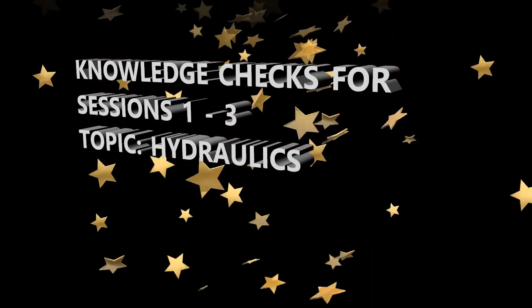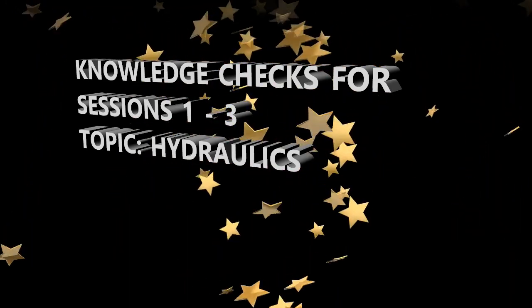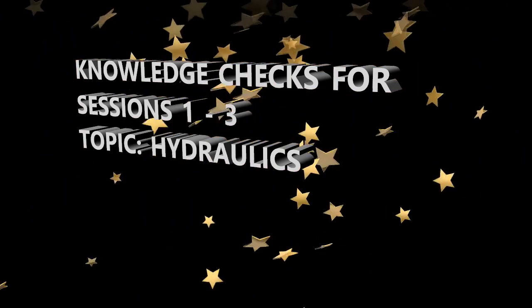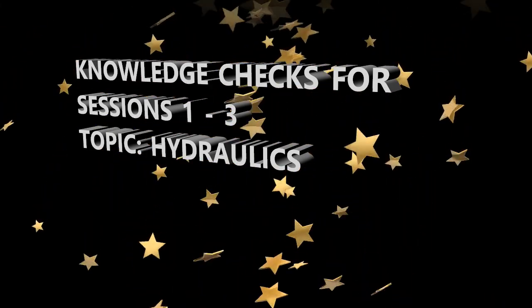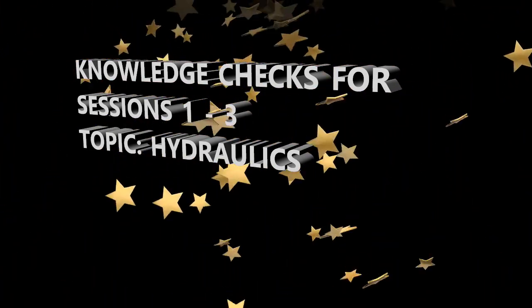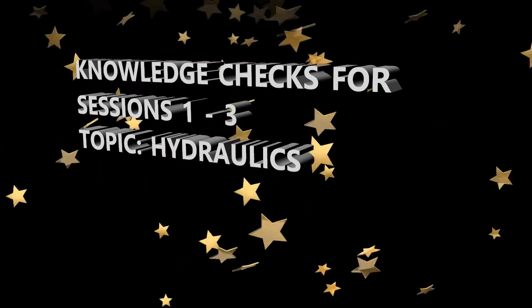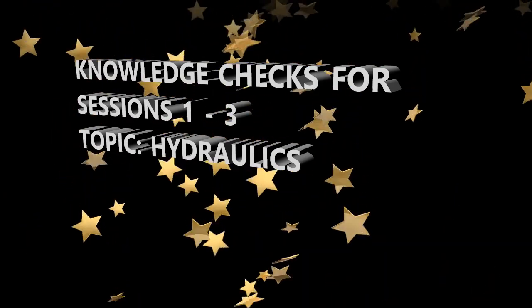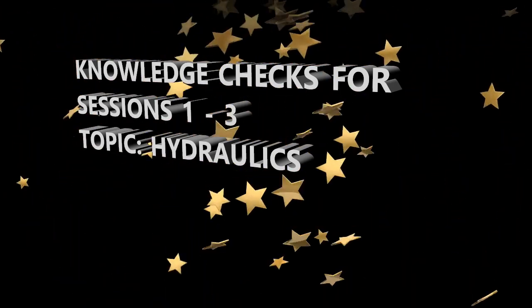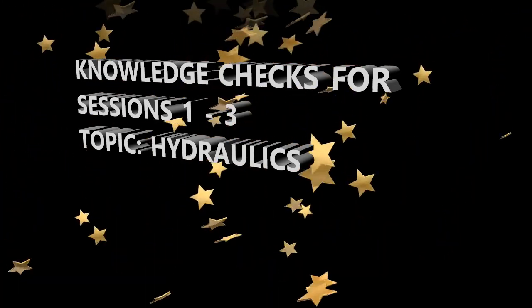The ground service panel is available for only the blue system. Is that true or false? Okay, it's false. It's available for all 3 systems. All right, question number 7. The ground service panel of the green system has a hand pump, a filter, and a selector valve so that any of the reservoirs can be filled from it. Is that true or false?